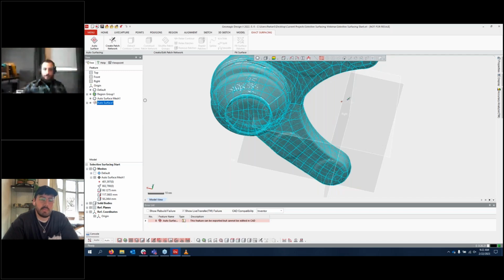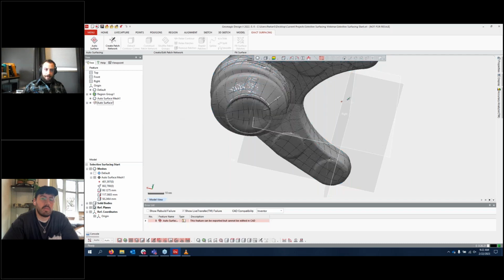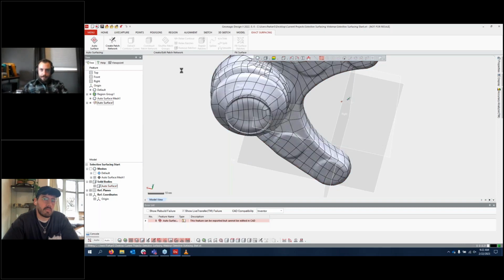But of course, I can get that CAD body there and do whatever it is that I'm going to do with that CAD body. So, like I said, I do have a solid body here, which is exactly what I want, and what we would expect. Since I'm on a webinar, I'm going to go ahead and say yes, because that's probably a good idea. There we go. So yeah, since it was exact surfacing, I should expect that the deviation overall is going to be fairly minimal between the scan and the CAD, which is exactly what I'm hoping to see. So I'll turn that off.